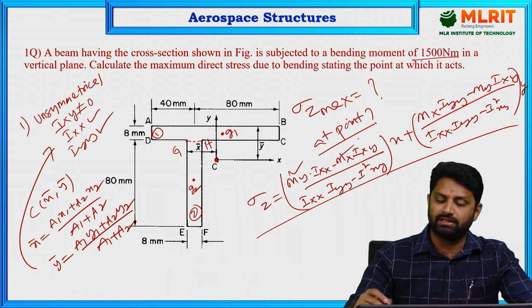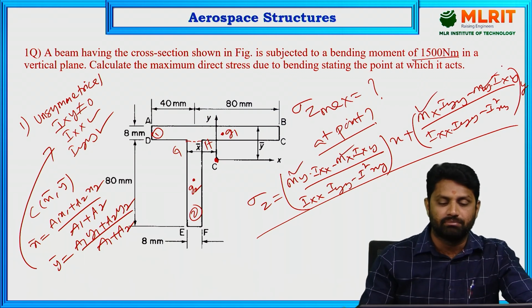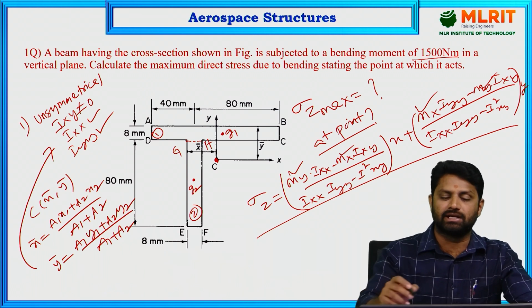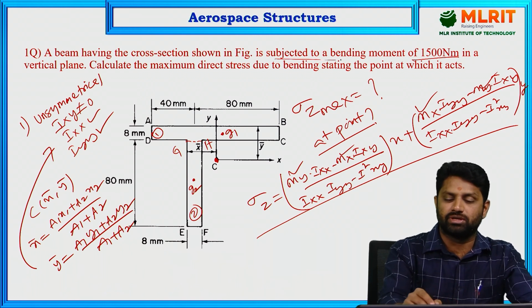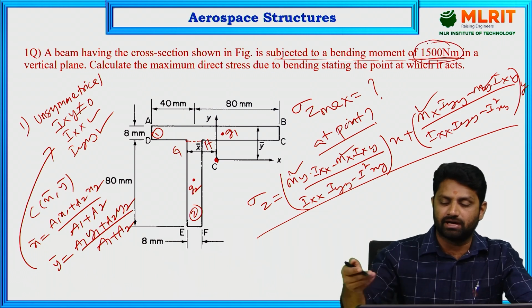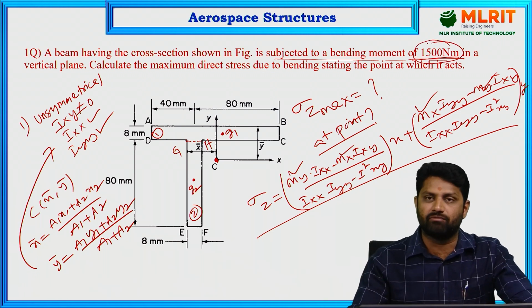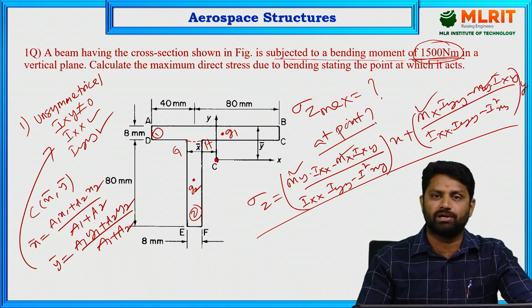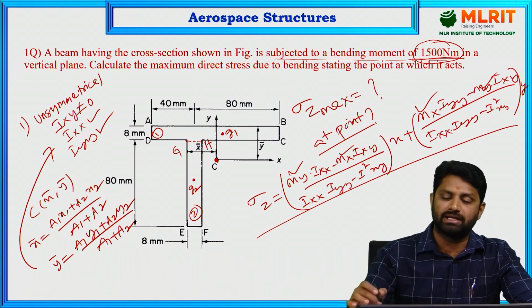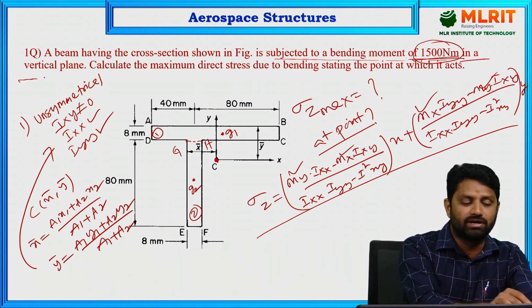Okay, everywhere in this here also Mx, My here. But in the question which we've seen here, he just mentioned it is subjected to a bending moment of 1500 Newton meter. He has not mentioned whether he has given Mx or My, but he just mentioned a bending moment of 1500 Newton meter. But he mentioned that it is applied in a vertical plane.